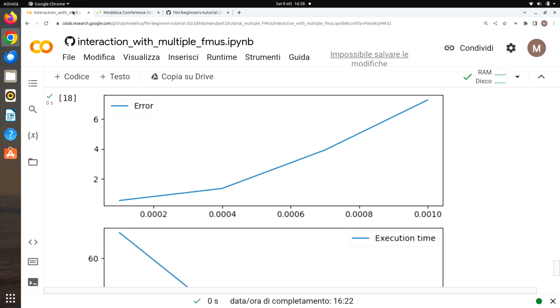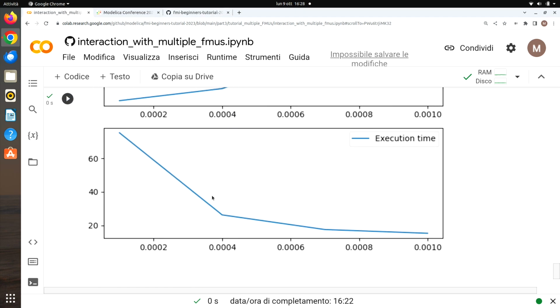And if you want to reduce the physical time for simulation, you only have the option to add more power. Come again? If you want to reduce the physical time, I think in mixed simulation with a real-time device, the only way is to add more power to the CPU. Yeah, or use one of these adaptive schemes. Then they can take large step sizes and slow down on critical parts of the simulation. Typically, if things are changing a lot, like in the beginning of the simulation, they take smaller steps, and then it stabilizes, and they take larger steps. But for real time, you would typically go for a fixed step, because it's predictable.